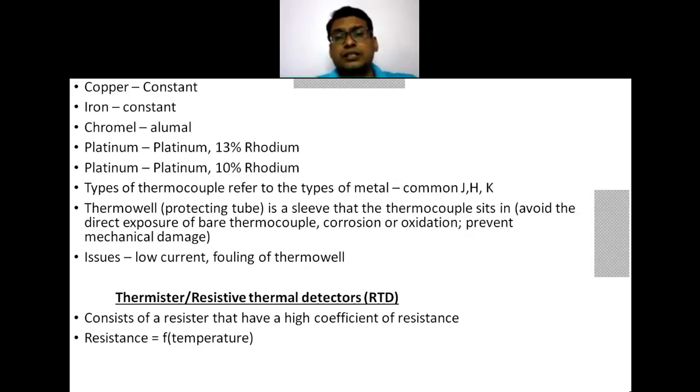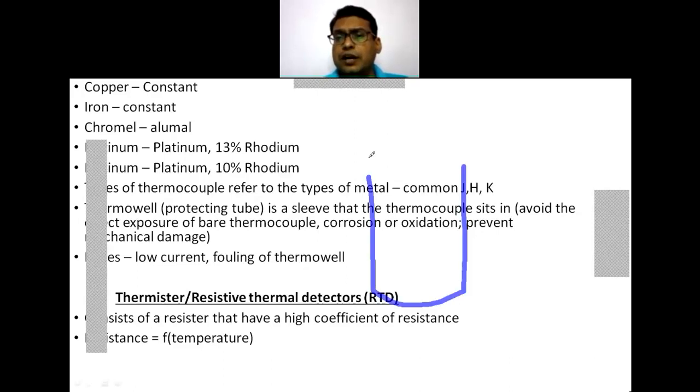Then there is a thermowell in which these thermocouples are inserted. These thermocouples are not directly exposed to the fluid, so for that purpose the thermowells are provided. That means if it is a vessel, I am not going to put a thermocouple directly inside it to measure the temperature. I am going to provide a thermowell